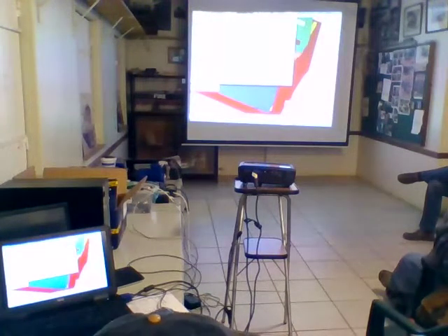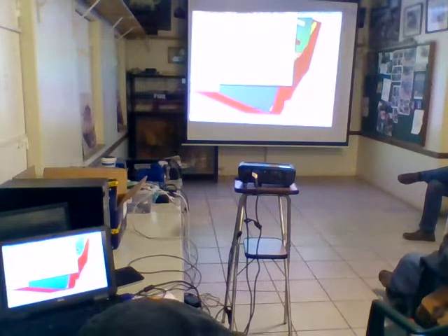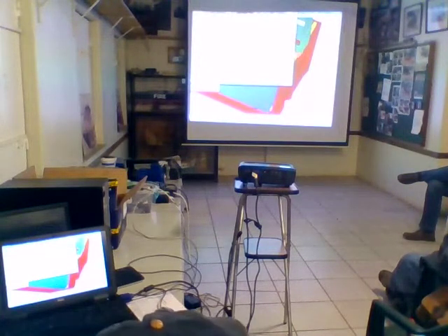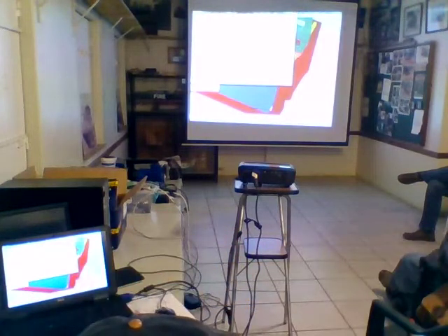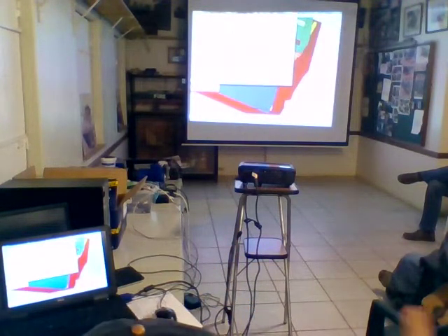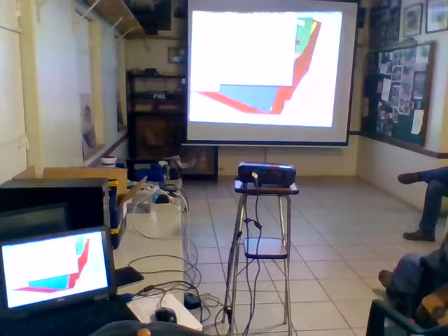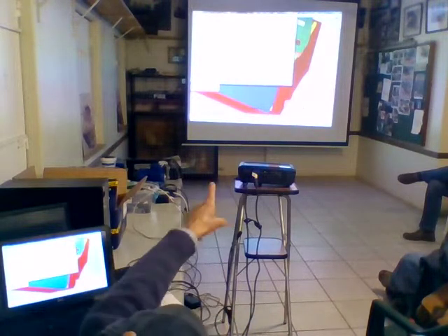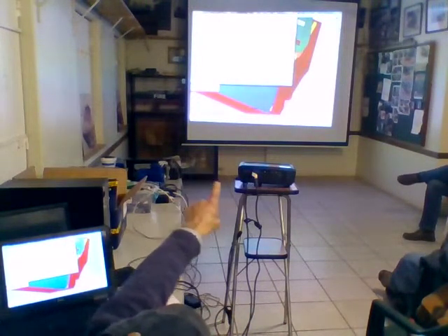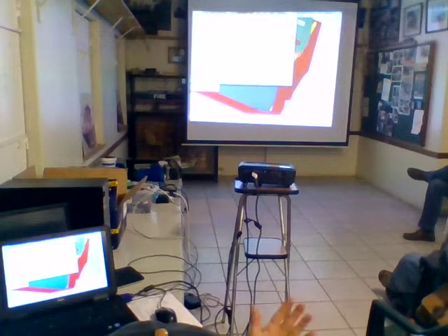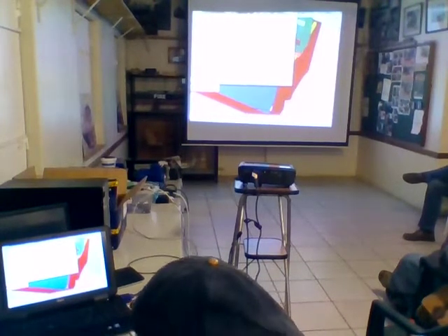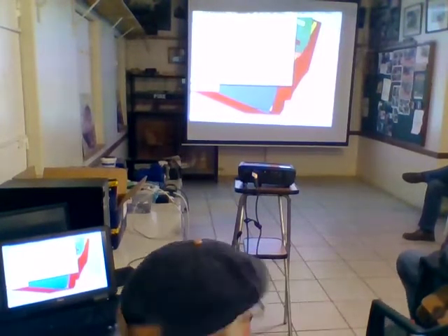The vertical stiffness, we normally want more stiffness, and it's easy to get vertical stiffness. But the lateral stiffness, especially on router type structures, where you've got the bridge across and your slides on the sides, is typically difficult to get. And here we see it also, the red is a little bit more than the green, which is in the forward direction. The red is the X.